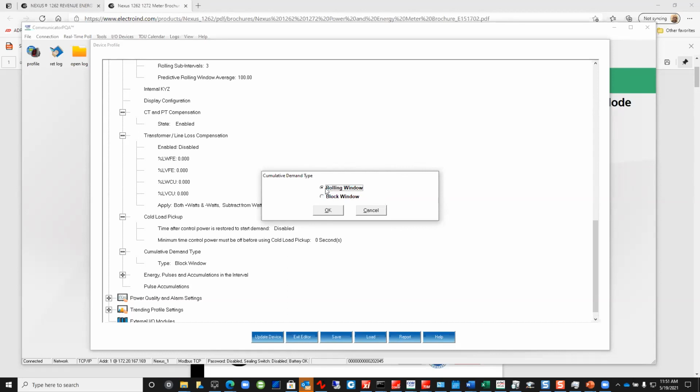Meanwhile, rolling is beneficial to investor-owned utilities who want to maximize the amount of revenue that they can gain. It also prevents people from trying to do split peaks and things like that. Let's say you have the meter set up for three 5-minute rolling periods in a 15-minute period. Whatever the highest value is in those three 5-minute periods would be submitted as the highest value, or the peak. That's a method used by most investor-owned utilities.